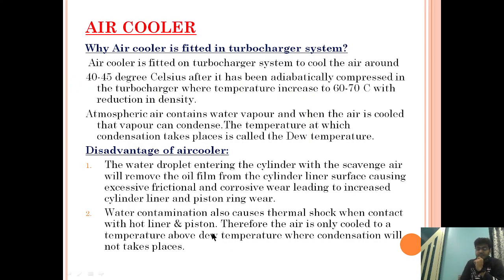Now the second problem, let's see. Not only one, there are two problems, very important, why we are fitting that water mist catcher. Water contamination also causes thermal shock when in contact with the hot liner and piston. Therefore, air is only cooled to a temperature above the dew point where condensation will not take place. Okay. Water contamination also causes thermal shock when in contact with the hot liner and piston, and therefore the air is only cooled to a temperature above the dew point where condensation will not take place.